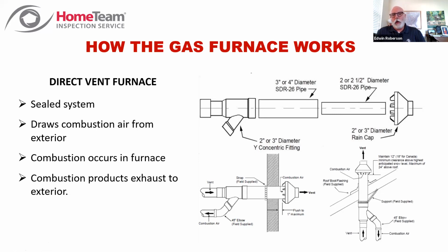Well, when they did that, they failed to convert to a direct vent furnace. In other words, they were still trying to draw combustion air from that crawl space and exhaust it outside. What you've got then is a very limited amount of combustion air in that sealed space. You need free flowing fresh air, an unlimited supply, in order to run a furnace.